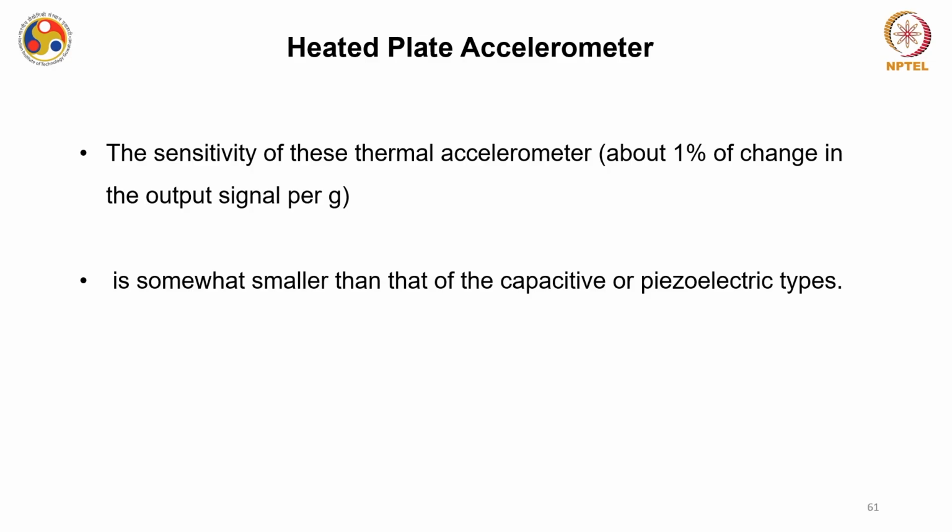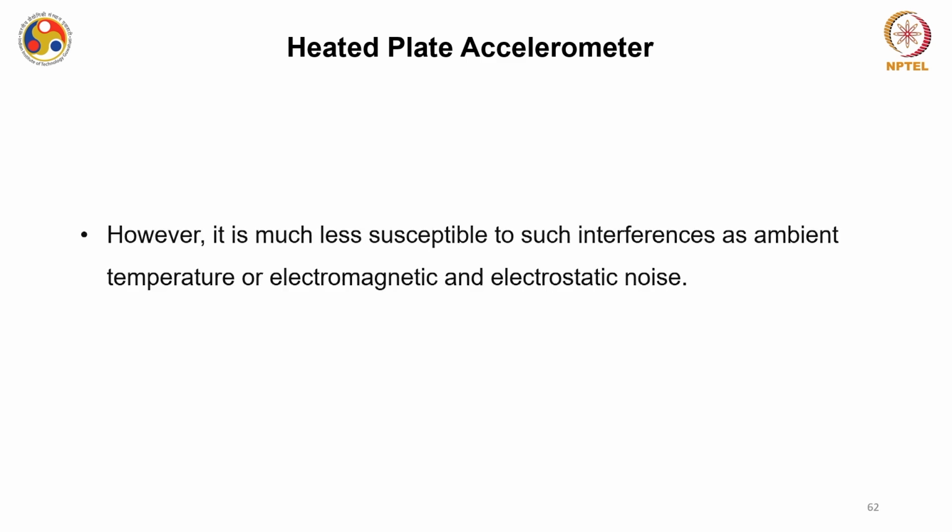The sensitivity of these thermal accelerometers is somewhat smaller than that of the capacitive or piezoelectric type. However, they have their own applications. The advantage of this kind of device is that it is much less susceptible to interferences, such as ambient temperature interference, electromagnetic interference, or electrostatic noise, because once the gases are trapped inside, it only depends on the internal conditions, not on the external conditions.